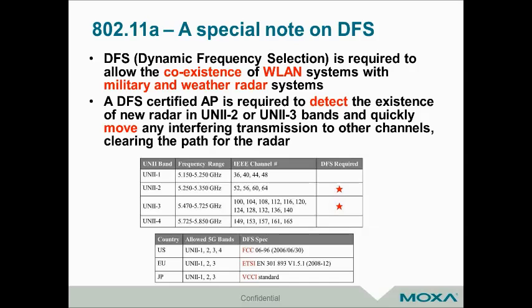So in this example here, the wireless devices are going to be installed on AGVs, which are moving throughout a facility. They're communicating to access points that are scattered throughout this major warehouse. And 802.11a is perfect for this, again, because you don't have to worry about any kind of electrical noise from the AGVs or any other devices in the area. 5 gigahertz tends to be very clean. It also tends to be very good in terms of bandwidth. It is max rated at about 54 megabits per second, so it is capable of transmitting some video over wireless if that's what you want to do with your application.